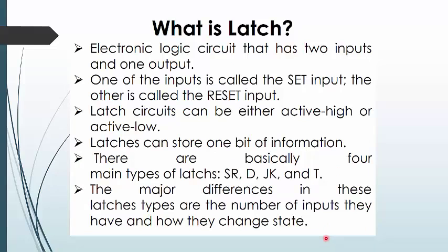Now, once again, we come to the case of latches, because I have mentioned that memory elements will be either level controlled, level triggered or edge triggered devices. The level triggered devices are named latches, while edge triggered devices are named flip flops.